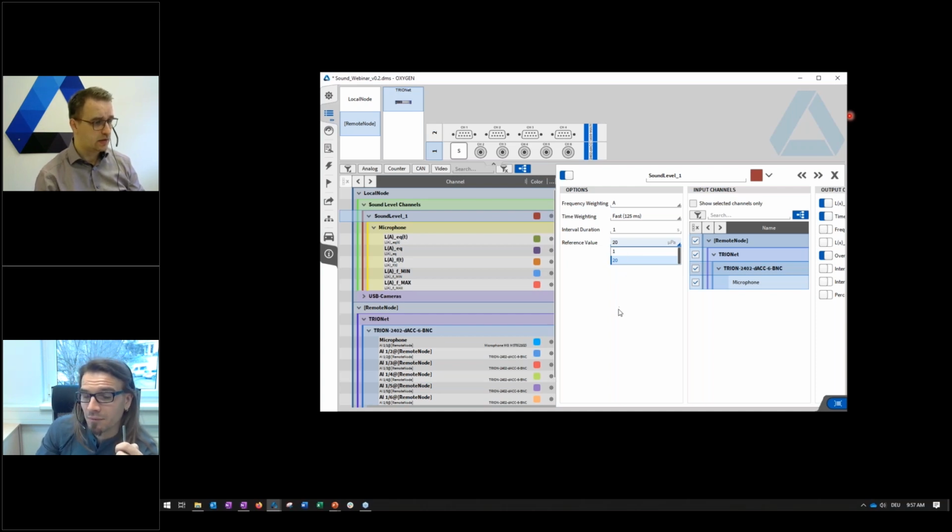That explains it. Okay, so we got actually a question by our audience, and it was asked on slide 13 with that analog meter that you had. Is the time delay linear across the frequencies, or does the filter add non-linearities? Does that question make sense to you, or can you answer that? In general, this is an all-pass filter, so there is, in the ideal case, no delay across the frequency range, but the delay is equal and the same across the frequency range. Okay,